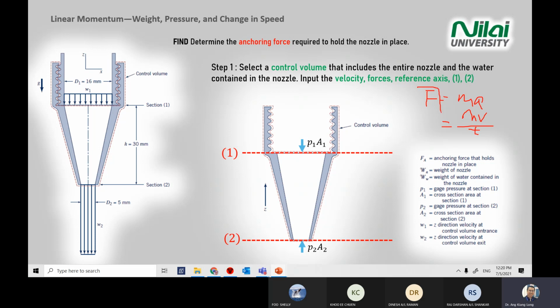So we are looking at forces, even though the question gives you pressure equal to force divided by A. So you are focusing on force. Rearrange this equation and you get force equal to pressure times area. So be careful when you draw your free body diagram, you are looking at forces F rather than pressure. So convert the pressure multiplied by area, and you get the force.